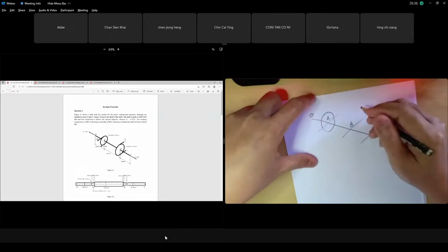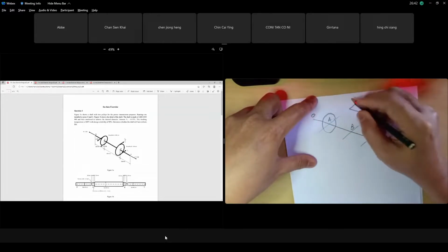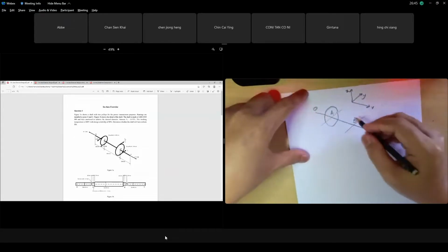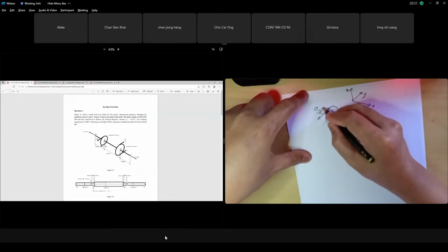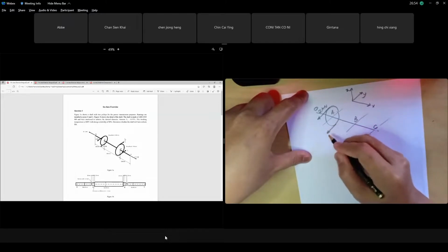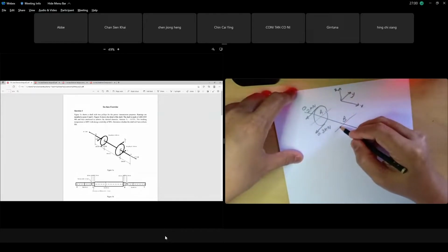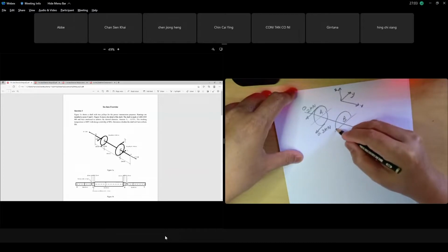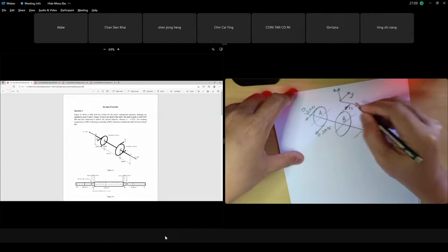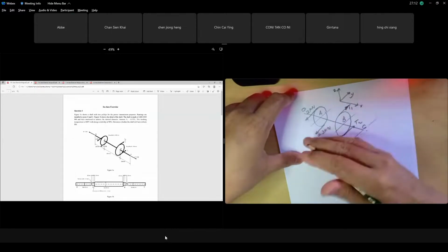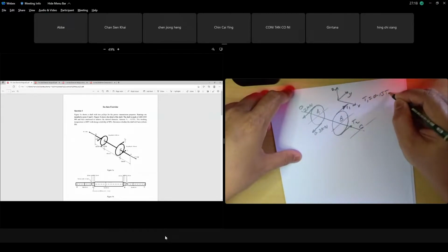Let's consider, because they didn't give the axis, let's put the axis like this. This is X, this is Y, and up is Z. We have tension at pulley A in the Y direction: one is 2 kilonewton, and one, also in the Y direction, is 0.3 kilonewton. At B, we have a bigger pulley with tension T1 and tension T2, both also in the Y direction. It's given that T1 equals 0.15 of T2.